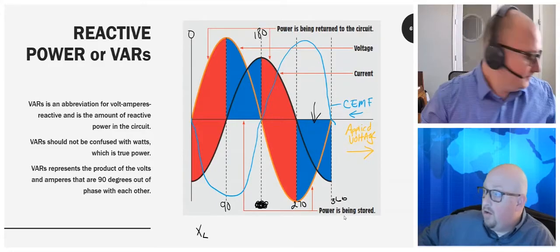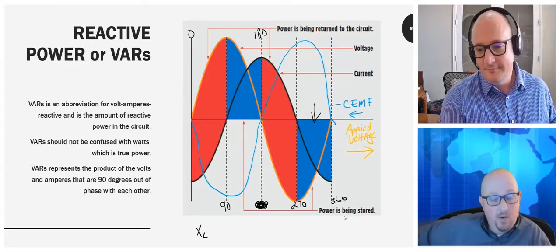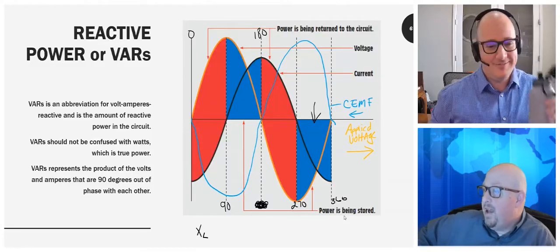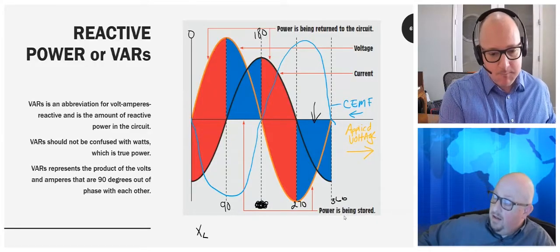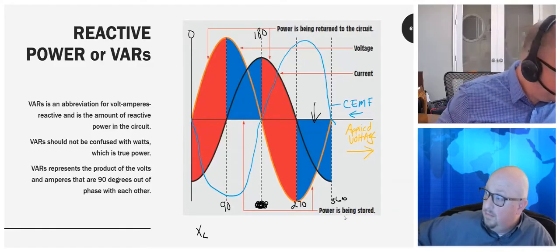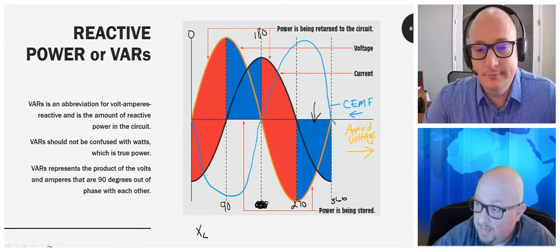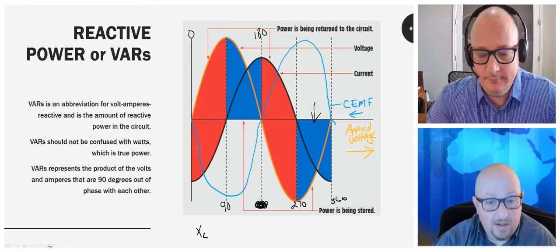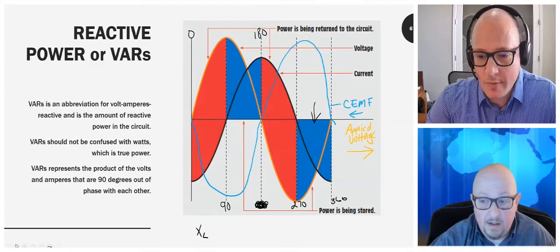So this counter electromotive force, CEMF. Boy, I can't speak today, so let's stick with the acronyms. With the CEMF being totally out of phase with the applied voltage, it acts as a form of impedance, opposition to current flow, and this is the basics of it. So how does this help me understand power factor? Why do I need to know this to actually understand power factor?